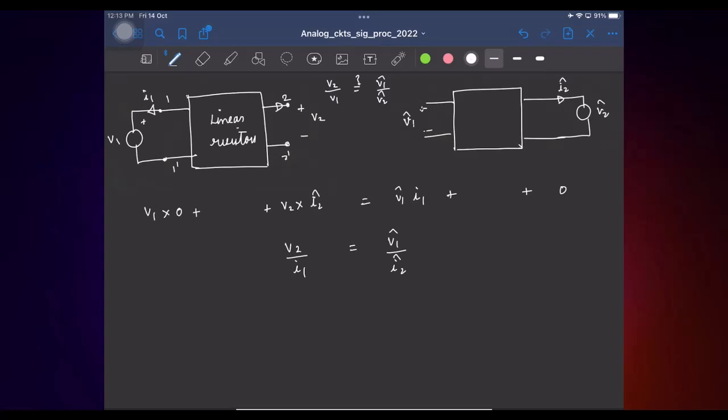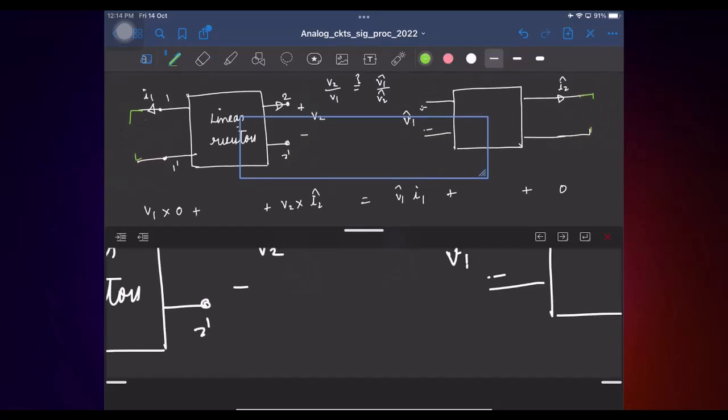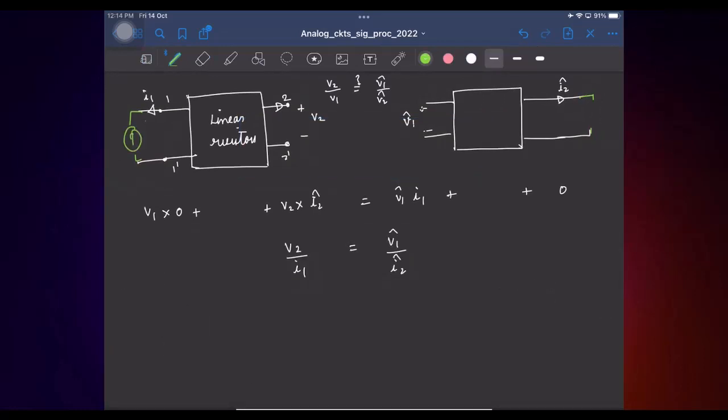Right? So what this says is the excitation at the input must be a current here. If you apply a current I1 here in this direction and measure the voltage here, that will be equal to the voltage you measure here if you apply the same current I2. So the excitation here should not now be a voltage. So the result we get is this has to be a current. And similarly here this should not be a voltage. Denominator is the input quantity. So basically I should be exciting with a current. And of course I can interchange the currents in the two. So I'll just see the current direction is like this.